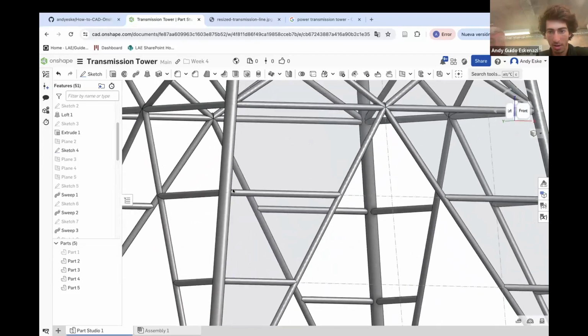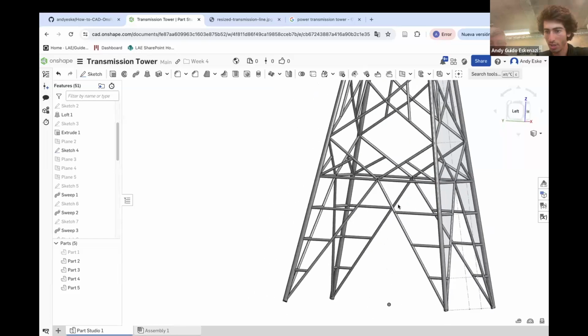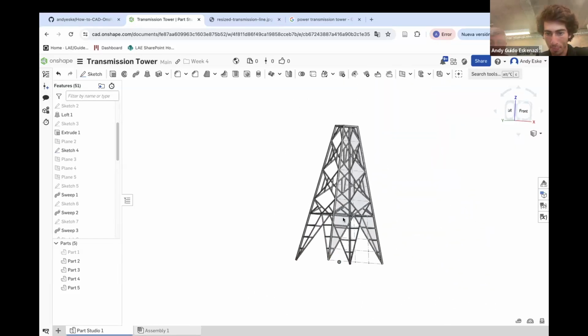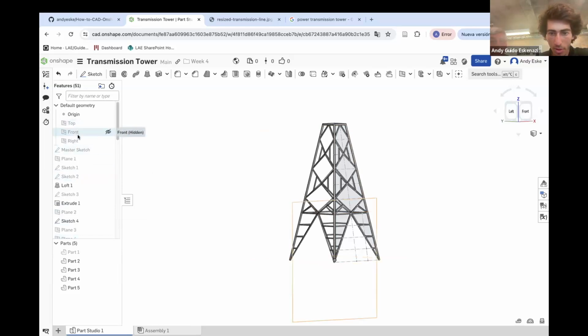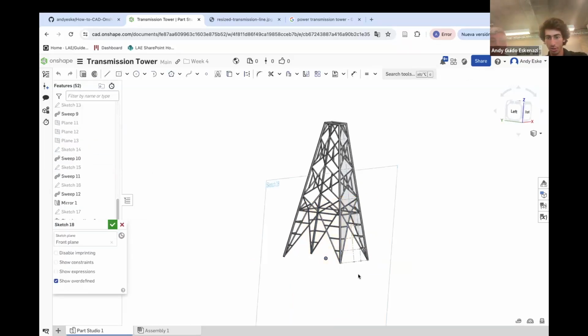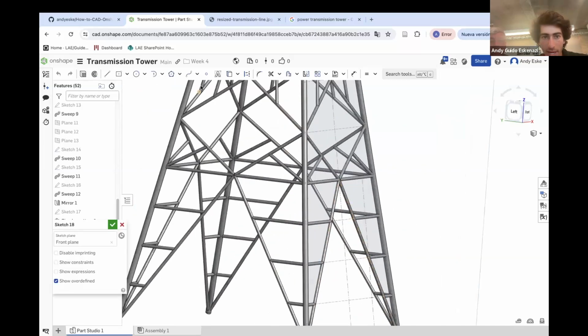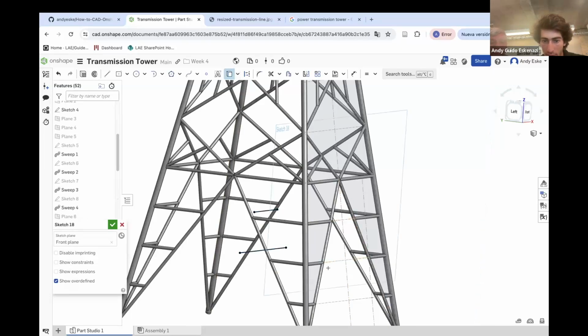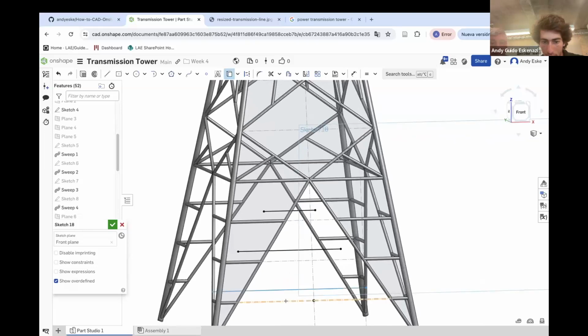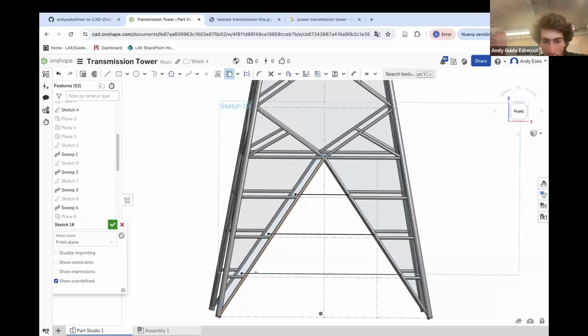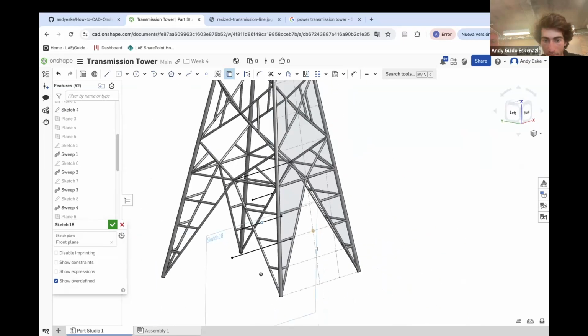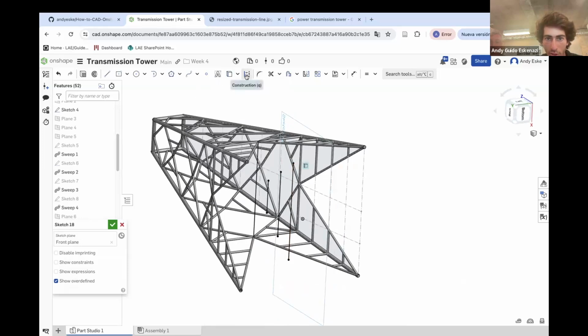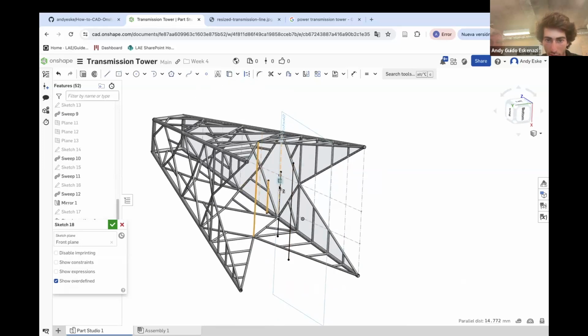So you have this sketch right here. I have an idea. What we're gonna do is we're gonna go to this plane. We're gonna do a sketch on that plane. And now in that plane, I'm gonna convert this line, this line, this line. So these lines, you see how they end there, and that line in there. Very good. Now, I'm gonna go here to construction and I'll make all of these construction lines.